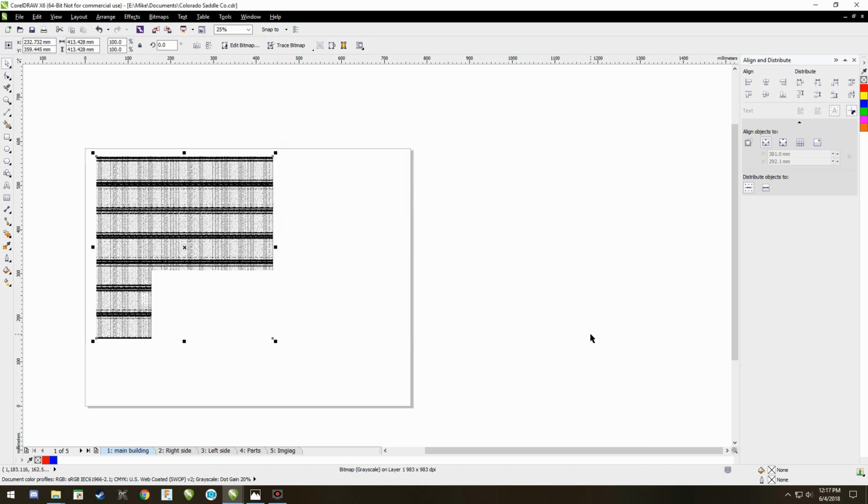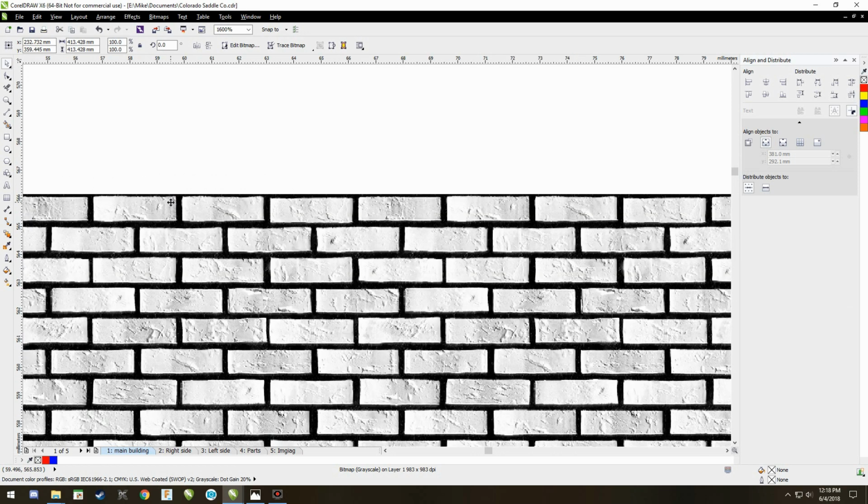Now, the disadvantage of saving in JPEG. When I take it to the laser, if you notice in there, it didn't take millimeters. It didn't say how big it is. It didn't ask those types of questions. That's because when you take it as a JPEG, I have to take it to the laser's computer, and I have to once again scale it down to that 3 millimeters across on the brick. So I will literally do the same thing there.